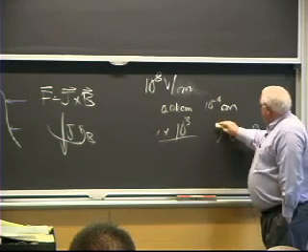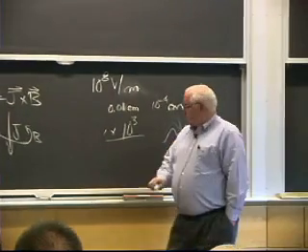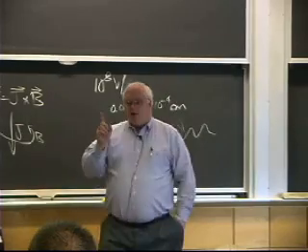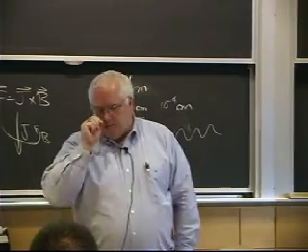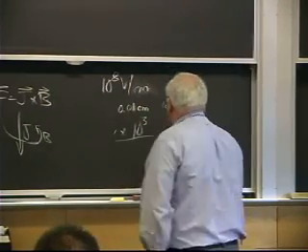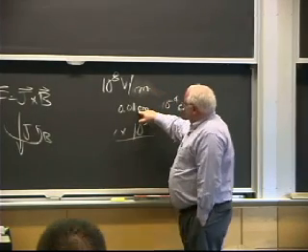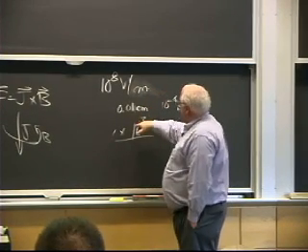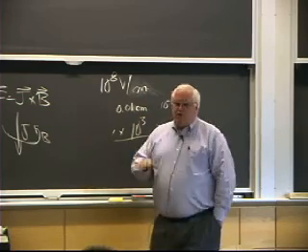And the electric field around the tip of one of these little asperities is magnified, okay? If I have a sharp point, I'll get a slight increase in the voltage. So even though this is about a human hair thick and 1,000 volts only gives me 10 to the 7th, I might get another factor of 10 from the surface roughness.